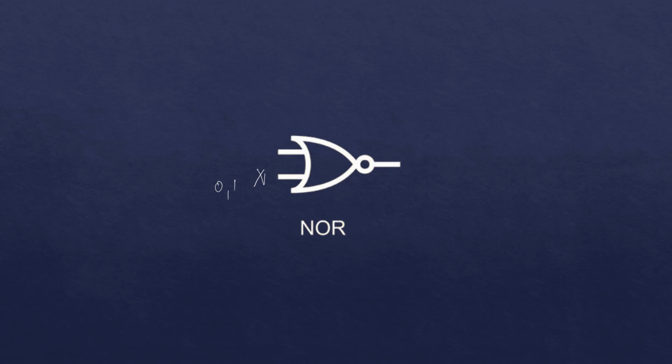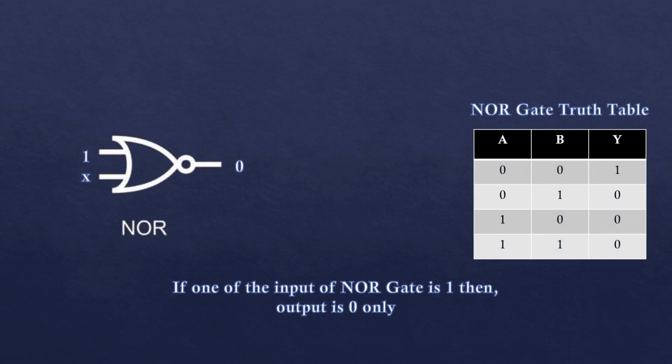Now let us understand what will happen if the value is 0. The NOR gate computes 0 plus x, whole bar. 0 plus x is x itself using the property, then whole bar, that's equal to x bar. So the output is x bar. Here the output value depends on the x value. If x is 0, then the output will be 1, and if x is 1, then the output will be 0. Now the same statement is given here: if one input of the NOR gate is 1, then the output is 0 only. Please try to remember this statement.